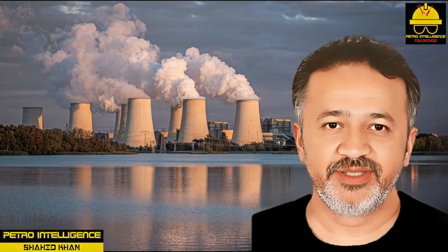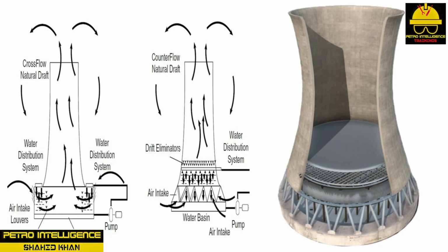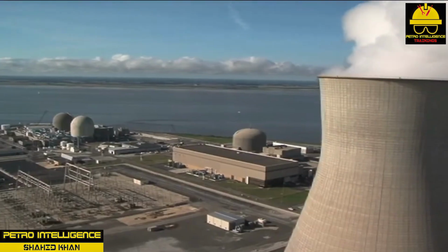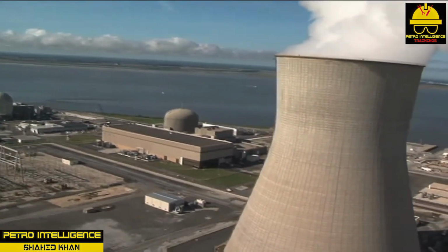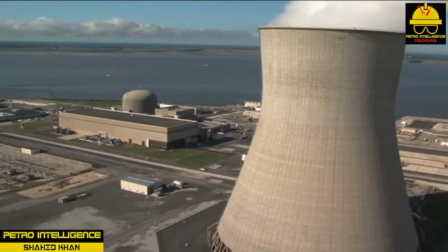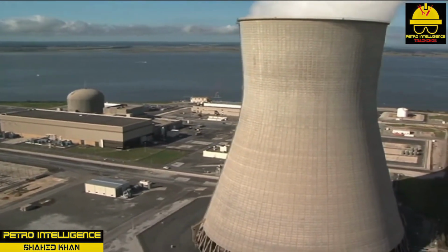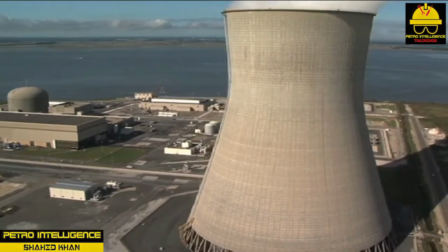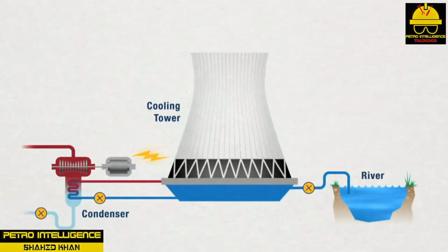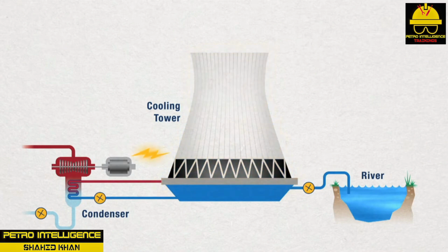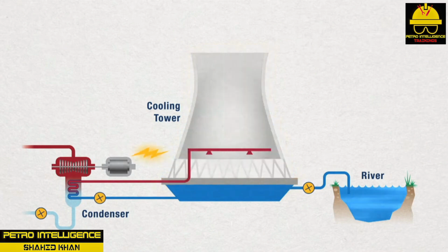Natural draft cooling tower. Hyperbolic or chimney towers are natural draft towers that have a large stack or chimney as shown in the picture. They usually are associated with power plant operation. Commercial towers are typically around 310 feet high with a lower diameter of 210 feet and a throat around 120 feet that gradually widens to 134 feet at the top. They are designed for flows in excess of 500,000 GPM, gallons per minute.